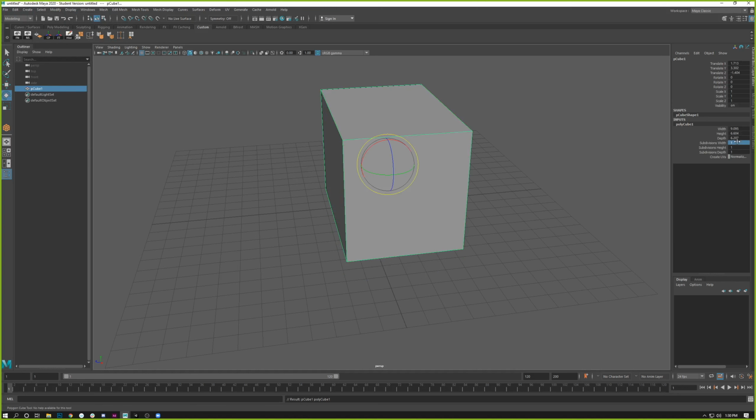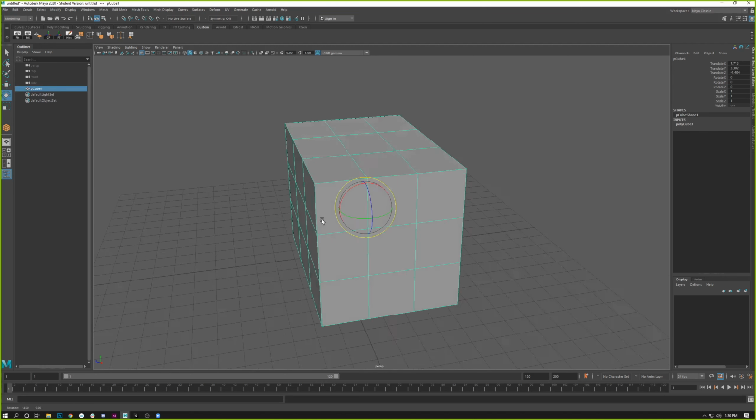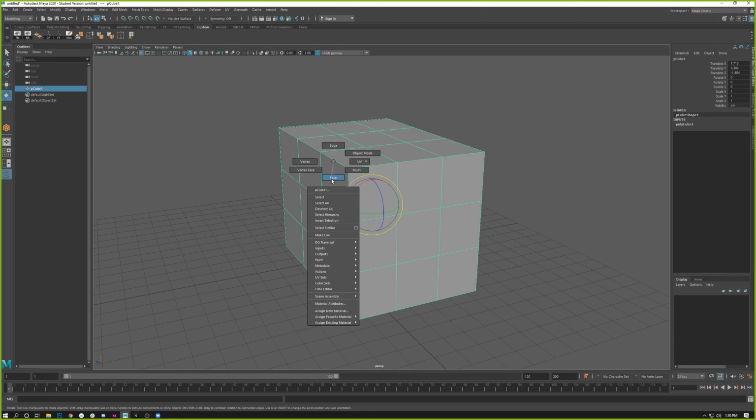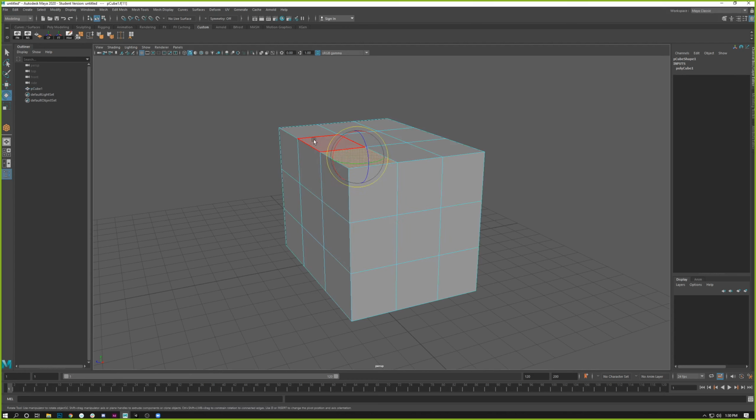if I come in here, I'm just going to increase the subdivisions. If you remember from our previous lecture, the Polygon Inputs, you select an object, go over to the inputs, and we can manipulate things over here. I'm going to increase the subdivisions at start, and you can see we have these divisions. Now, a lot of students will start adding divisions to things, and there's lots of ways to do this, so it's not the only way. I'm just showing you the way you guys already know.